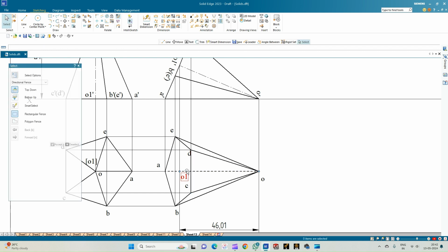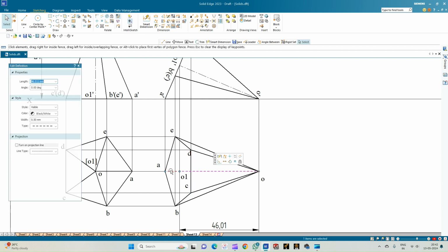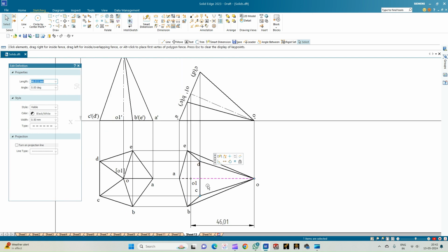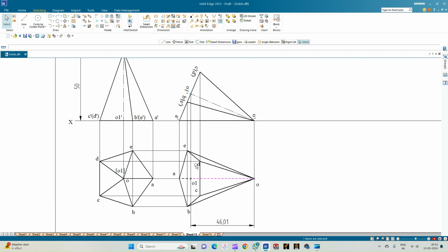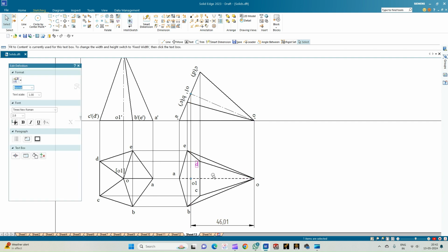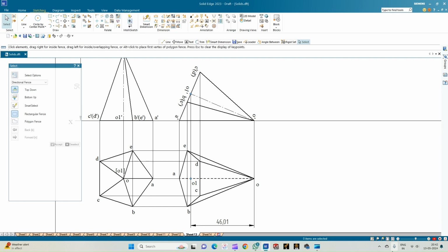So you can just see that the axis line is distinct. It should not be a continuous line or else you'll not be getting this point O1 for the next position. So use this as a broken line, that is A to O1 and then from O1 to O. Okay, so you do not have to show this as axis line. It is understood that the edge line is overlapping on the axis line. So now we'll see how to construct the beta angle for this.